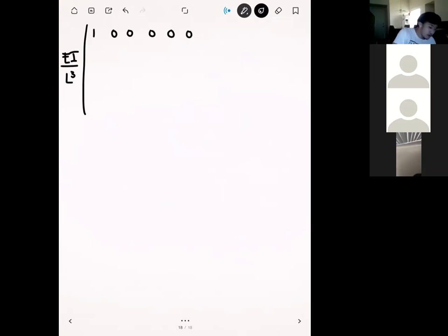Our second row is also replaced. Then we start filling in our values from before: minus 12, minus 6L, 24, 0, minus 12, 6L, then 6L, 2L squared, 0, 8L squared, minus 6L, 2L squared.